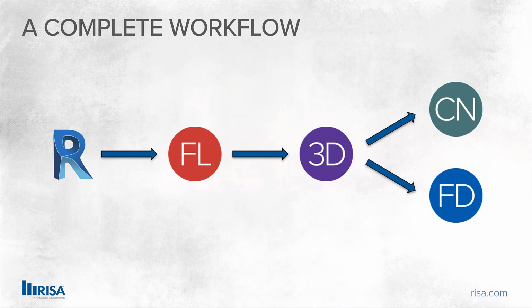One thing we didn't show in this workflow, from a time perspective, is that we can actually go back into Revit. At different stages of the design, for instance once we finish the gravity design with composites, if we wanted to send that information with reactions, number of studs, camber, and so on back into Revit, we would use the same feature in Revit. Instead of export, we use import, right? And we'd import the information from that same RISAFloor model.